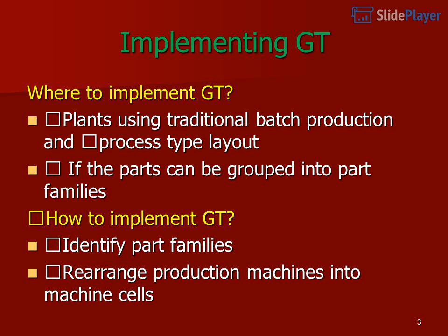Implementing GT. Where to implement GT? Plants using traditional batch production and process type layout, if the parts can be grouped into part families. How to implement GT? Identify part families. Rearrange production machines into machine cells.